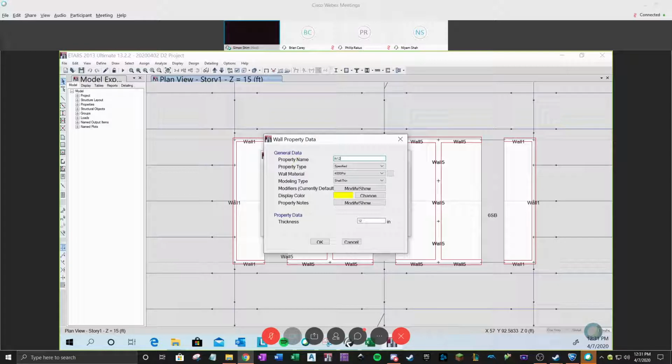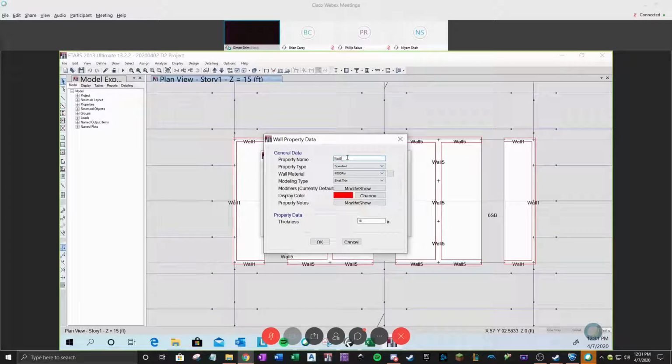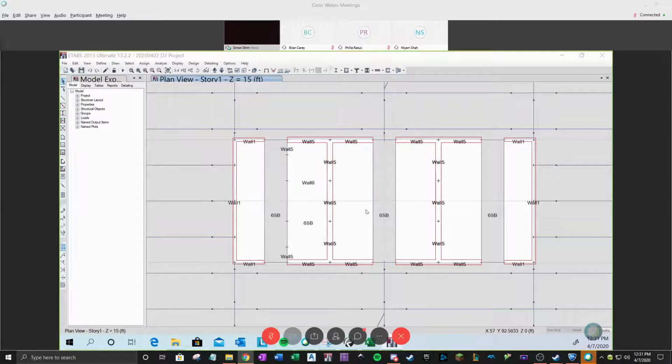So I'm going to use the same thing, wall 12, C4. So wall thickness 12, concrete strength 4. I usually see wall 18 and C4. So we need more, 15 and C4, because currently we are using 4,000 psi, but obviously we need more than that, thicker than that. So let me just reshape.